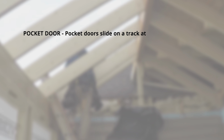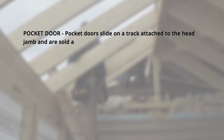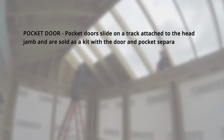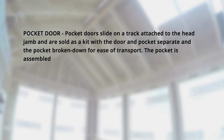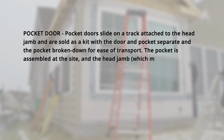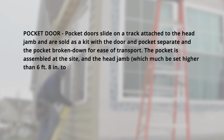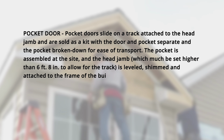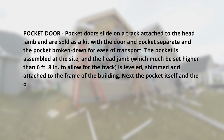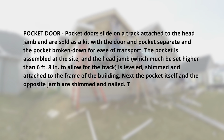Doors. Pocket door. Pocket doors slide on a track attached to the head jamb and are sold as a kit with the door and pocket separate and the pocket broken down for ease of transport. The pocket is assembled at the site and the head jamb, which must be set higher than 6 feet 8 inches to allow for the track, is leveled, shimmed, and attached to the frame of the building. Next, the pocket itself and the opposite jamb are shimmed and nailed.